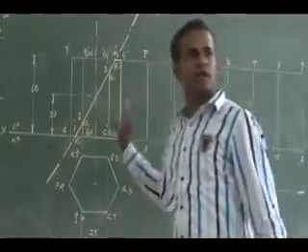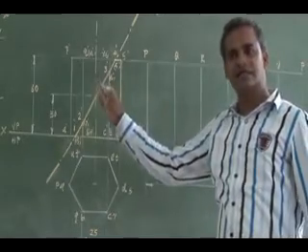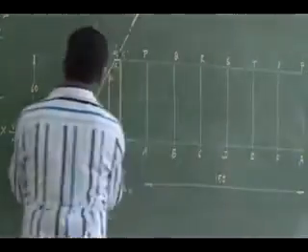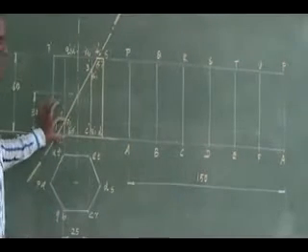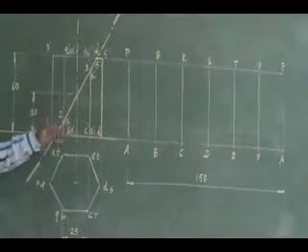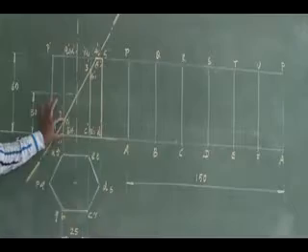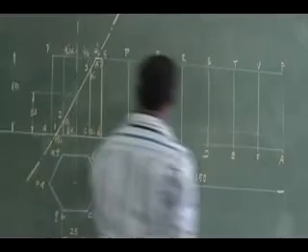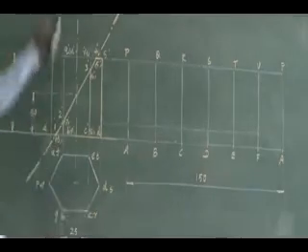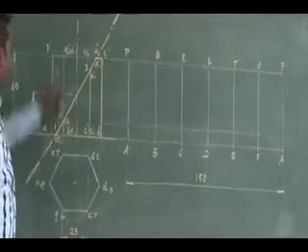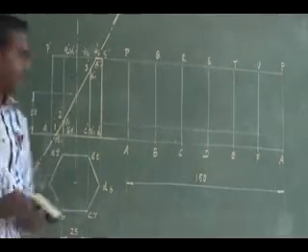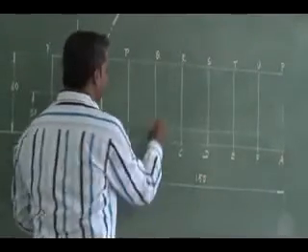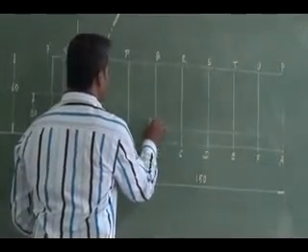So how can I mark it? Anybody? I can extend a horizontal parallel line from there. Otherwise, you can measure this height from the base. You can measure it. Cutting point height on the appropriate vertical edge, you can mark it. Right? Otherwise you draw a parallel. Cutting point 2 is on vertical edge BQ. So you just mark that on vertical edge BQ. So that is my cutting point 2.